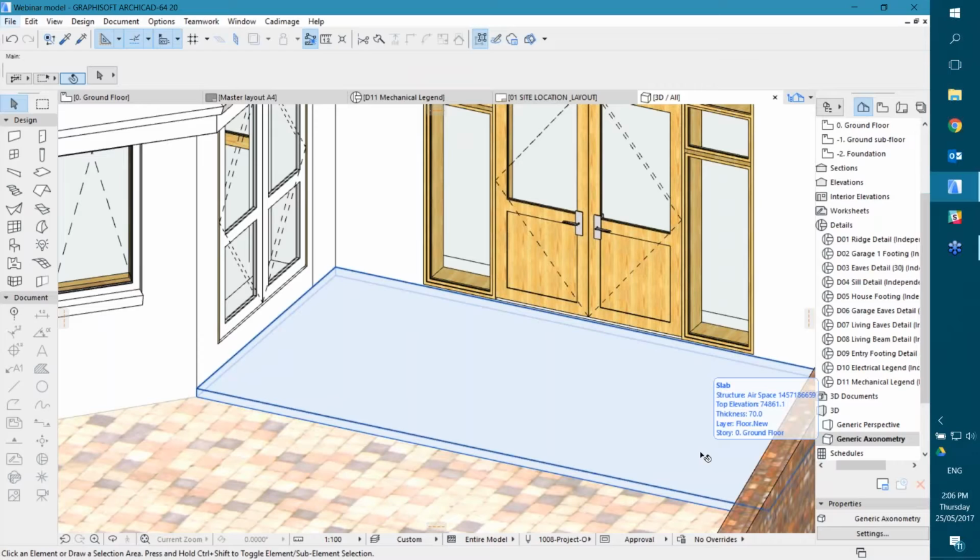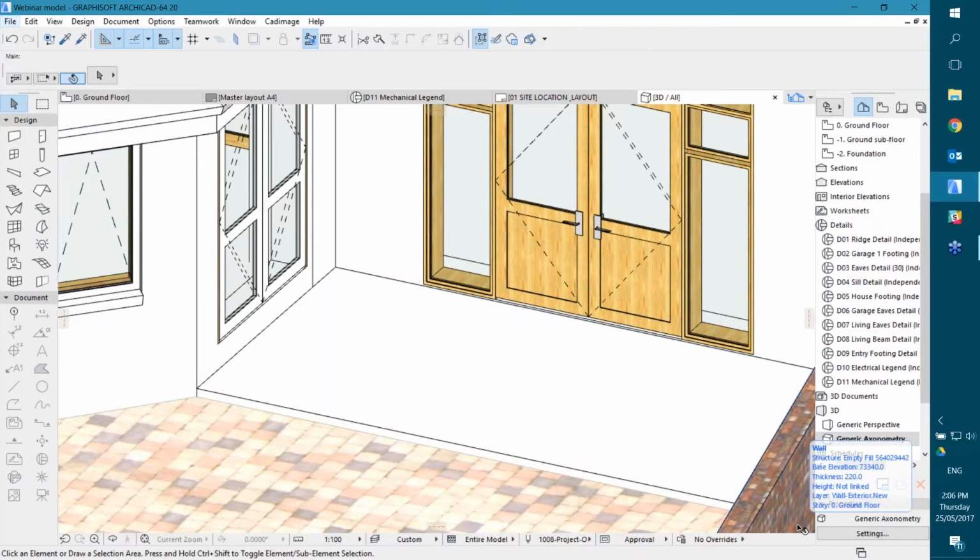This would work as well, the problems being that it would take a very long time to set up and it would be very difficult to keep it in the shape of the deck if you modified the shape of the slab that's underneath there. But it would look good if you cut a section or elevation view, and it'll look good in 3D, obviously. So where the Coverings tool aims to help here is to come in and give you the best of both worlds.